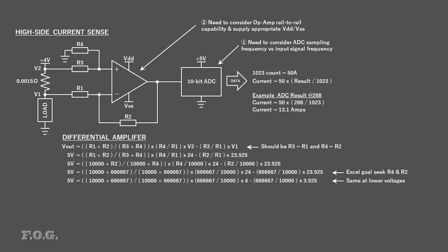And we'll keep it simple. We'll just change the R3 value to be right on the edge of a 1% tolerance. So that will be a 9.9 kilo ohm resistor instead of 10k. So we'll redo that same calculation again using the 4 volt supply and that gives us a result of 5.04 volts, or a 0.8% error compared to what we'd expected. It's not so bad, I guess.